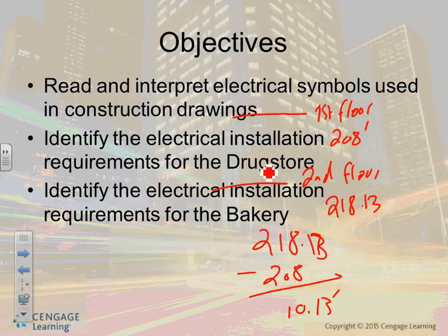Why is it important? Because if it's steel studs, depending on the wiring, typically we use MC cable. The wiring method that we use is MC cable versus an NM cable. I don't think of any engineering work where you use other than MC cable. Yes, MC cable is the cable of choice for all commercial buildings. So you will learn that one as you go through.